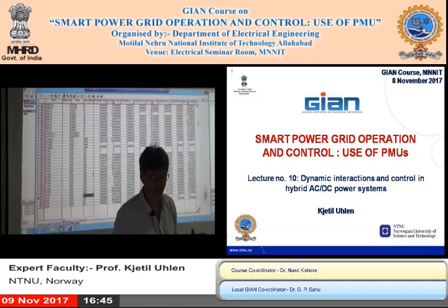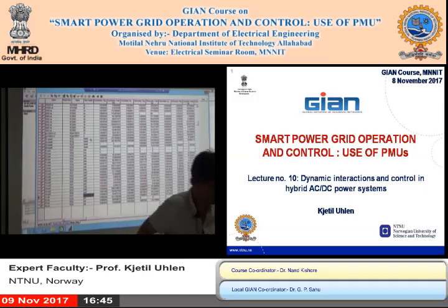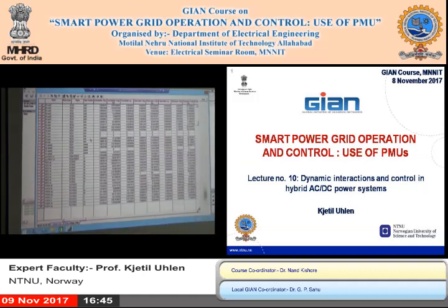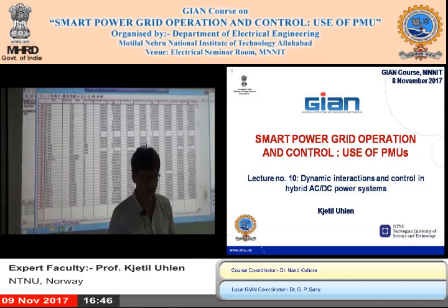Referring to what we talked about yesterday, when we set up the equations, we get 4 equations for speed, since we have 4 generators. We get 4 equations for the transient internal voltage, which is these 4, I think. And we got 4 equations for each of the damper windings. So everything is there.